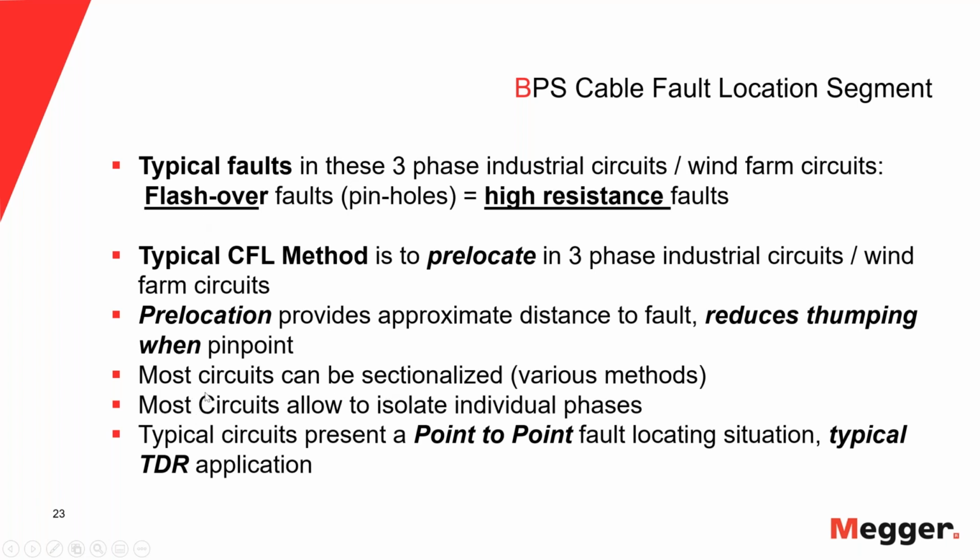That allows us also, because most circuits allow us to isolate individual phases. That's very important because you will see the difference when we talk about network systems where that is not always the case. But in these circuits, we should be able to isolate individual phases, which again makes it a whole lot easier to fault locate. And so these circuits present really a point-to-point scenario. The TDR is a very good tool to apply to point-to-point fault locating scenarios. And that's what we have for the most part in these type circuits.